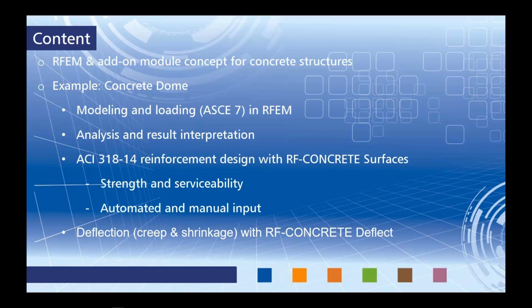But today we're going to utilize the add-on modules within RFEM to do ACI 318 reinforcement design, and today we'll be utilizing RF-CONCRETE Surfaces. Now this add-on module allows us to run both strength and serviceability design, and I want to show you both automated and manual input of the reinforcement areas. Lastly, we'll take a look at deflection with considerations to creep and shrinkage with the module extension RF-CONCRETE Deflect.